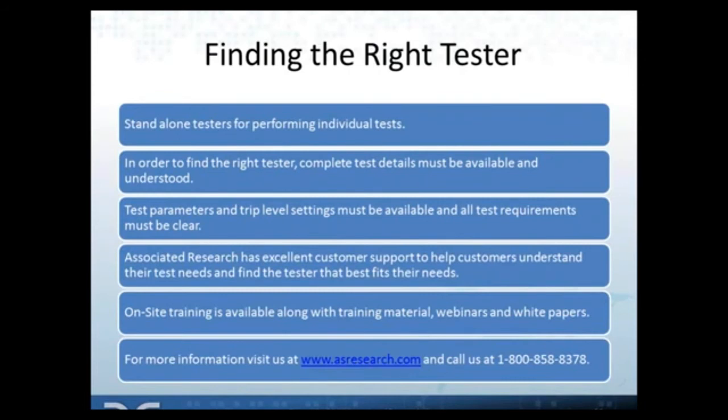We also have standalone testers for performing individual tests. In some of the previous pictures where I showed some examples of a device being connected to a ground bond tester, we have testers that can just perform ground bond tests at different current levels. We have testers that can just perform the hipot test, the insulation resistance test, and just the line leakage test. And again, we have complete 4-in-1 or 5-in-1 testers as well, which are complete electrical safety compliance